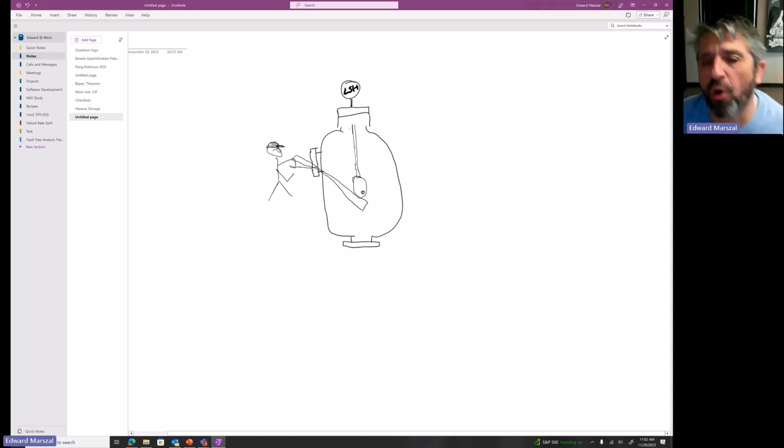If there's a hole in this float, when the vessel fills up with liquid, the liquid is going to go into the float, fill it up, and it will never float. That is a dangerous failure for sure, because in a high level trip situation, it's going to prevent this device from doing its job.